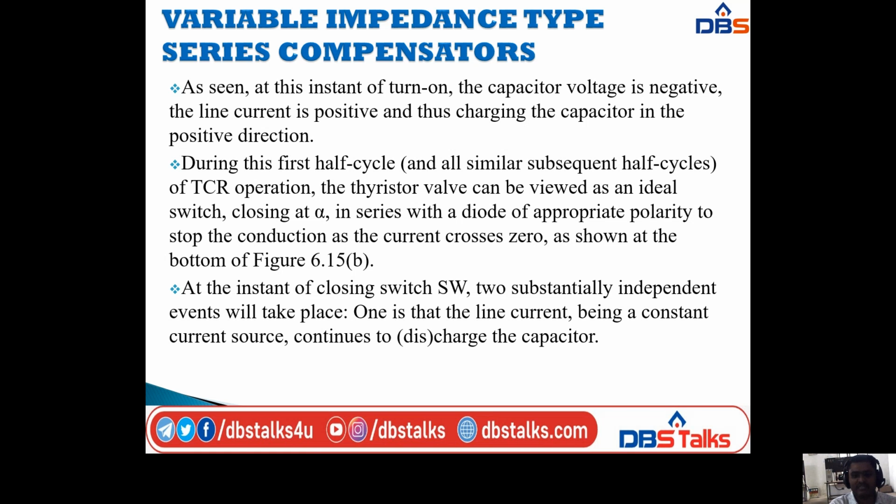During the first half cycle, and all similar subsequent half cycles of TCR operation, the thyristor valve can be viewed as an ideal switch closing at alpha in series with the diode. I am explaining the B diagram. In the B diagram we take one diode and switch, and this switch is connected to the reactor, and this reactor and diode are connected to the capacitor.